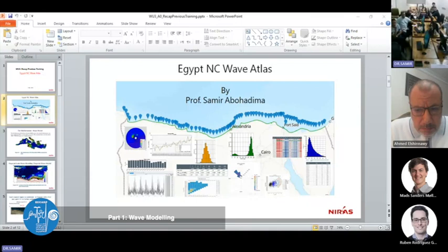At each point, we plot and watch figures for time series, which is the point parameters of DFS0. It includes spectral equivalent significant wave height, maximum wave height, peak wave period, mean wave period, zero crossing wave period, wave energy period, peak wave direction, mean wave direction, direction standard deviation, all these outputs, plus in the other file, spectral points.dfsu, the wave spectrum.